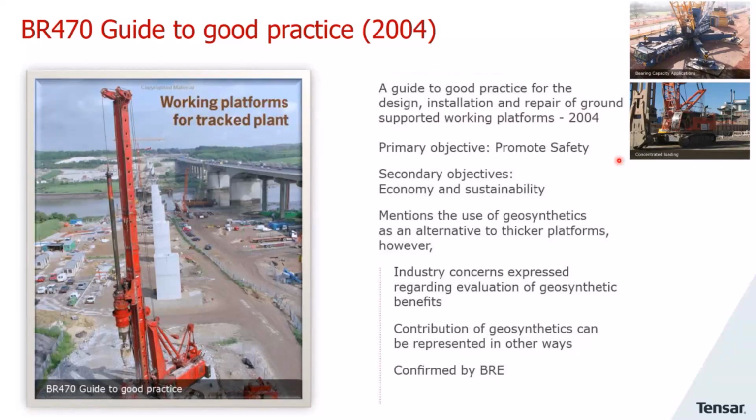But it is a key document for working platform designs in the United Kingdom, written by the Building Research Establishment under the direction of the Federation of Piling Specialists back in 2004. The BR470 is not a design code, but it is a good practice guideline to the design, installation, operation, maintenance, and repair of ground support working platforms.